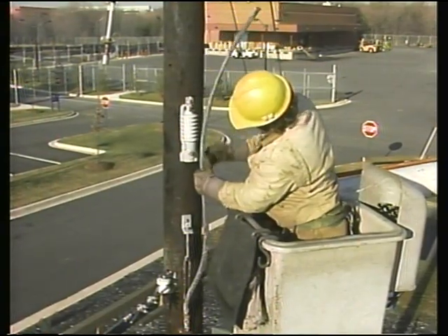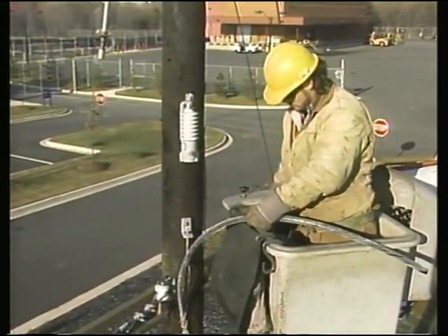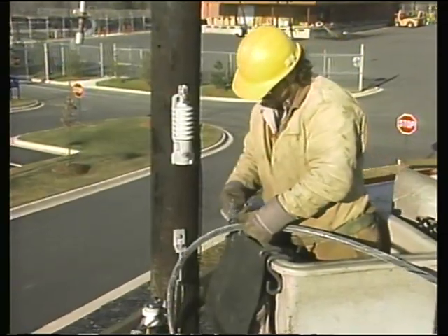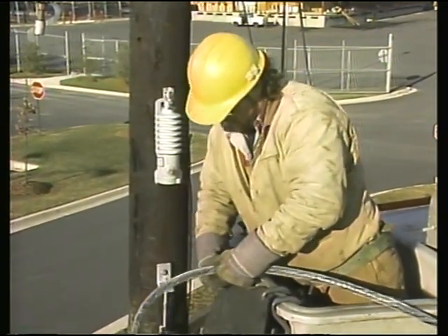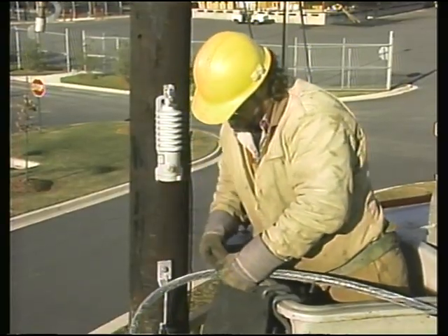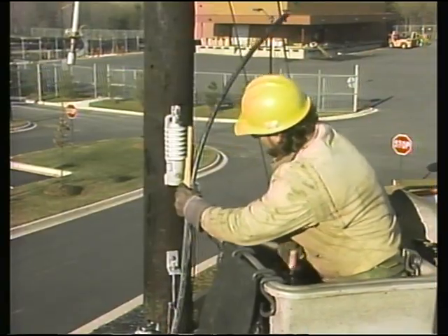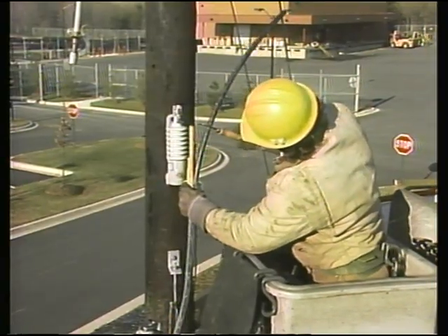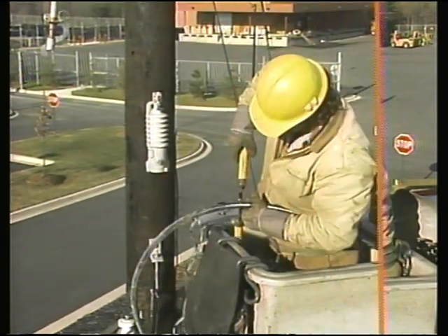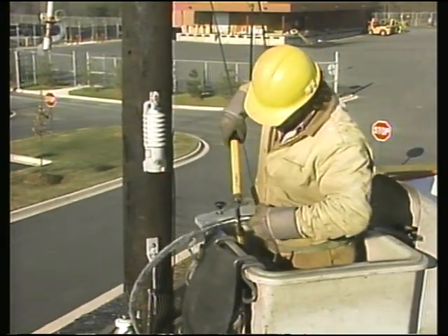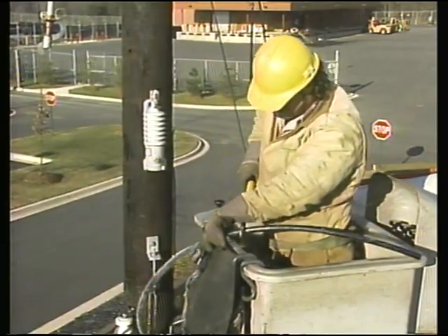Then the cable is held alongside the terminator and marked with a wire. The wire indicates the point to which the concentric wires will be pulled back before the cable is cut. This ensures that enough of the concentric wiring will remain after the final cable cut is made. After the concentric wires are pulled back, another mark is made to indicate where the cable is to be cut. Then the cable is cut to its final length and the cable layers are prepared according to the termination instructions.